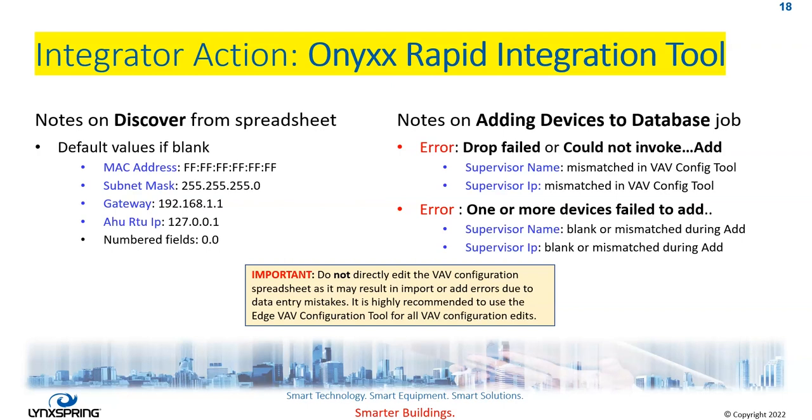Without the tool, originally, we just had a spreadsheet for you to put all the entries in. However, to get that out of the way, the configuration tool was the easiest thing that we came up with to make sure that you don't edit that directly. Sometimes you still have to, but if you have different types of VAVs, like for example, FPB boxes and VAV boxes that are named FPB VAV or FPB01 VAV01, FPB2 VAV02, you can create two separate spreadsheets and import them